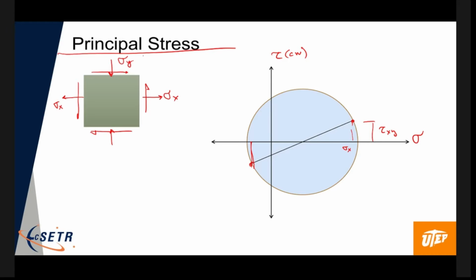Obviously you're given values here, but this is the Mohr circle corresponding to it. This point here is sigma x, tau xy. This is sigma y, which is negative tau xy. And every point on this circle corresponds to a different stress transformation. It's looking at it in a different coordinate system.